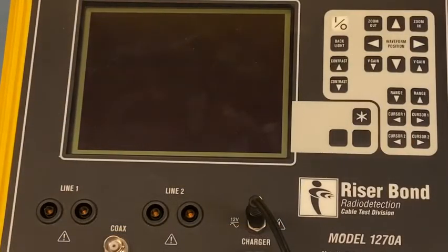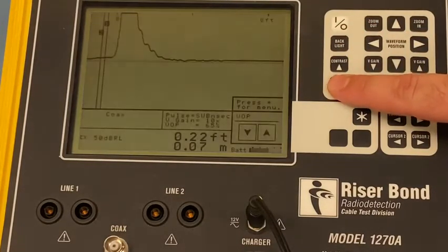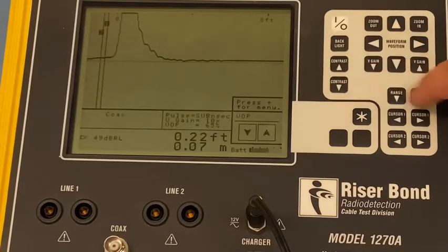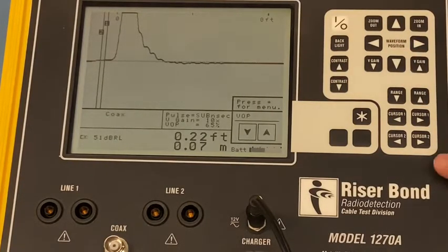Following the steps in the TDR job aid, first turn on your TDR. Ours is already on. Adjust the display controls for a clear, bright trace. Adjust the vertical position control to center the display. Line up the rise of the incident pulse on a vertical line.